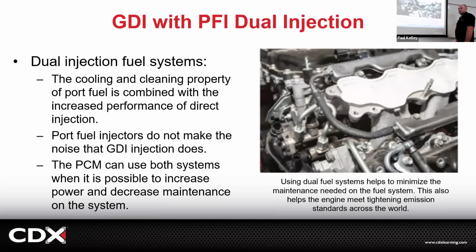What if we did both? Okay, now this is a positive Toyota thing. Domestics don't do this. Toyota, Lexus do this. They'll have direct injection with all the power and all the fuel economy and all the positives. But you know what they'll periodically do? They'll spray the port fuel injectors just to clean the valves. Are you serious?